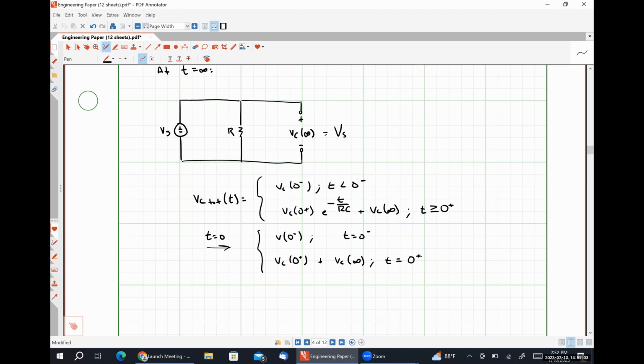So what we need to do is we need to correct. So the problem here is that mathematically, this voltage gets applied at all points in time because it's just a constant value. And so it's slightly skewing our results. So what we're going to do is simply subtract that value out over here. So we're going to have VC at 0 plus minus VC at infinity.